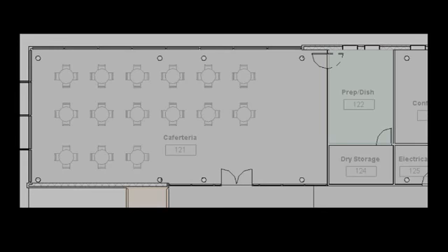I thought about how I was going to explain this, and I know if I just showed you the script, I couldn't. So I made a flow diagram, if you will. First we're going to make points in the room, this is to put our supply diffusers. Then we're going to move those points, shifting them over about half of the distance that we put them. This is ideal for placing diffusers. You could even go as far as using the manufacturing data.